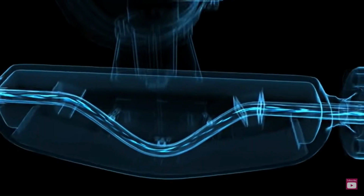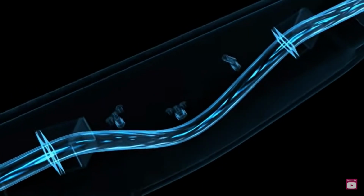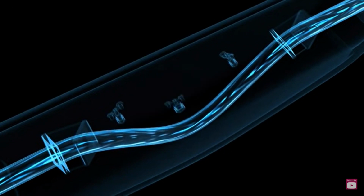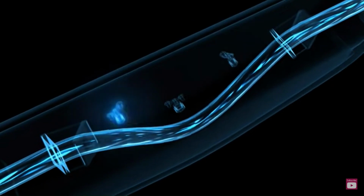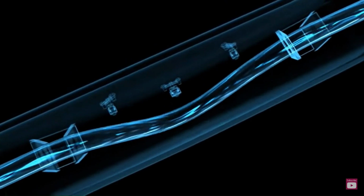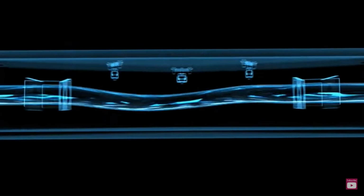A tube is located inside each Coriolis flow meter. An exciter causes this tube to oscillate constantly, here in an exaggerated example. If there is no flow, the measuring tube oscillates uniformly. Sensors are located at the inlet and outlet and register this basic oscillation precisely. As soon as the fluid starts to flow in the measuring tube, however, additional twisting is imposed on the oscillation as a result of the liquid's inertia.